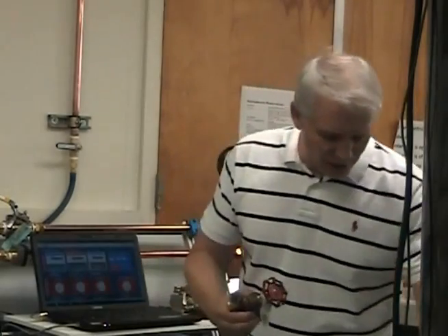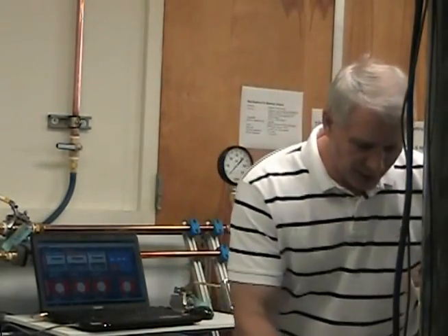And then we have number 1 here, it's a check valve. You can see how that operates. It only allows flow in one direction. And then we have a few others. Just look, these two look identical, but they are not. If you look inside the valve, you'll see how they operate. Each one of them will have a different loss coefficient, and they have their own applications. So part of your lab report is to identify these and identify applications and the loss coefficients.